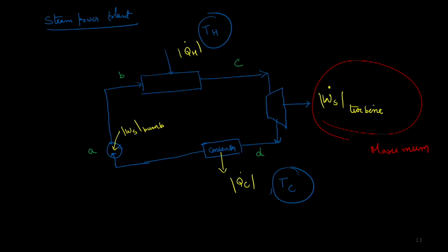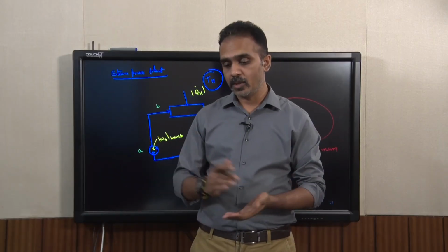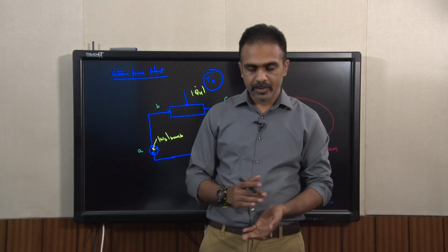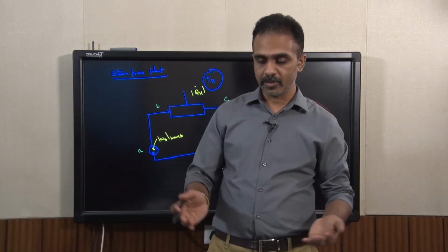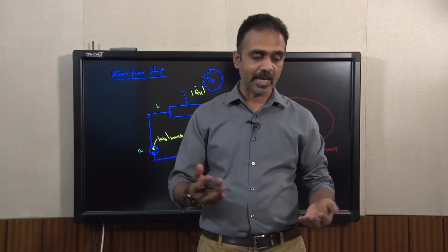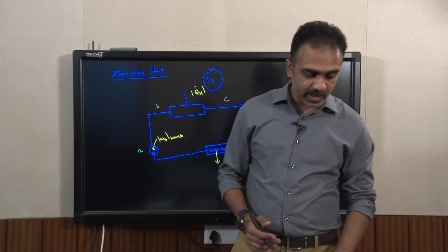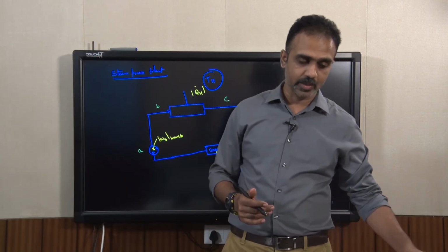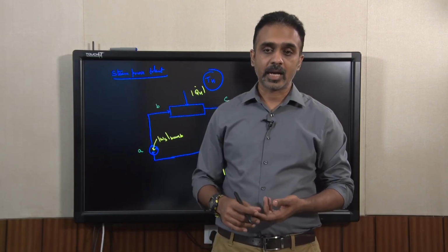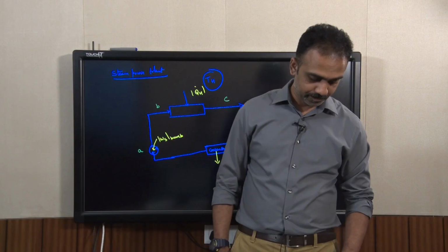by using the ideas we learned in the Carnot engine concept. It's going to be 1 minus Tc over Th, and that would be the maximum value, but because of the irreversibilities in the processes and everything else that goes on, the real value is going to be much lower than the maximum value. So these are some of the applications of what we learned today in terms of the second law, the Carnot engine, and thermal efficiency of a Carnot engine.